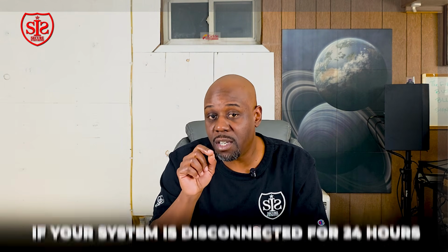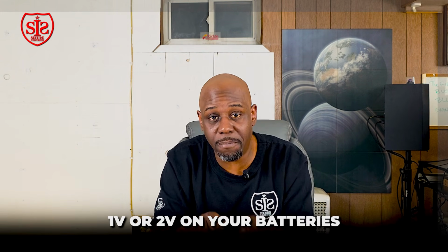And I first learned in real time, when you have a voice system, depending if you have the right size batteries, this is where you can tell if you have the right size batteries or not. If your system is disconnected for 24 hours, you come in, you sound the alarm, and if that alarm goes off for 15 minutes and you lose no more than 1 or 2 volts on your batteries, you have a good fire alarm system. The battery calculations are good to go. And that's straight from the NFPA book that I've seen in real time. That code right there will always be imprinted in my brain because I've seen it with my hands, I've seen it with my eyes, and I've seen it in real time.